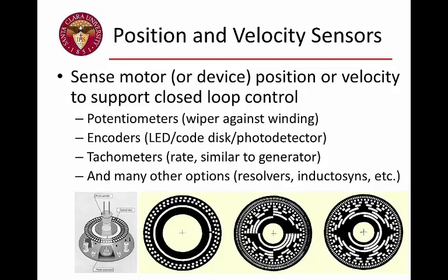The one on the right is a slightly different version I mentioned briefly in class called gray code, which is another binary code. Again, it's binary in the sense it uses ones and zeros, but it's not a standard number system. And so if you compare it to standard binary, the sequencing of the ones and zeros occurs in a different order in order to convey information about the count. And the reason it does that is it gives you tolerance for things like mechanical misalignment in the mask and some other interesting properties. We'll follow up on that topic in class.